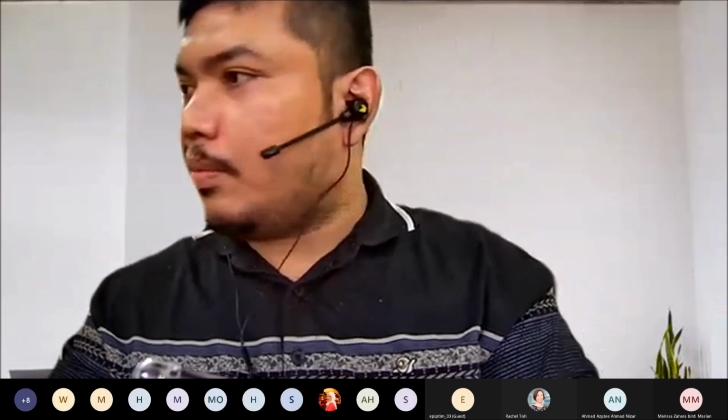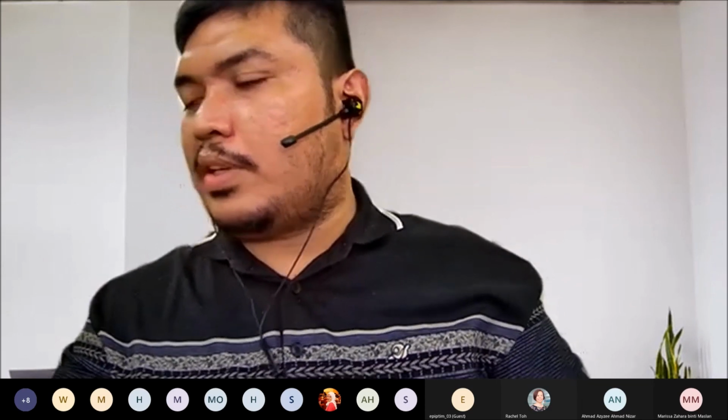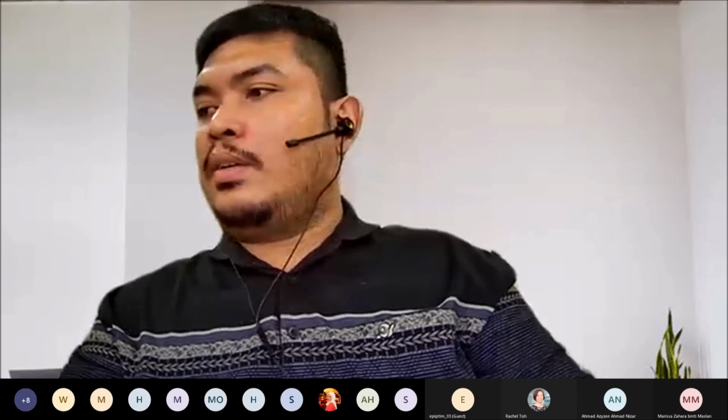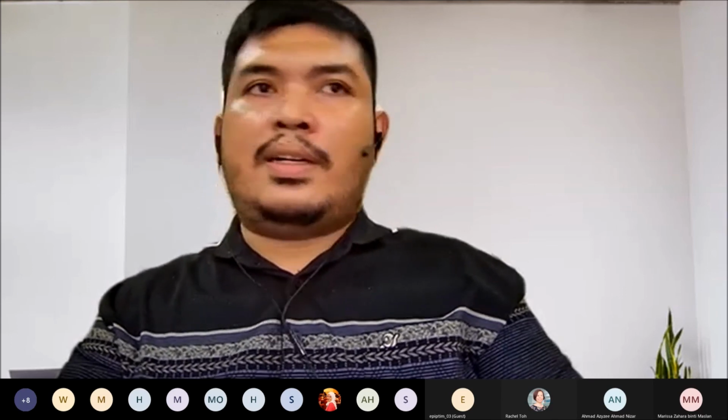Okay, this is a question from Shafiq Nasir. Zamri, is it possible to collect data like downtime or best cycle time using the Factory IO simulation? Actually, Factory IO cannot collect the data. Factory IO cannot collect downtime and best cycle time using this software. But you can use Visual Components software to take this data. Even in Visual Components, you can also take the human step count. For example, when they go from one station to another, how many steps they use, all of this you can get with Visual Components, but Factory IO cannot.